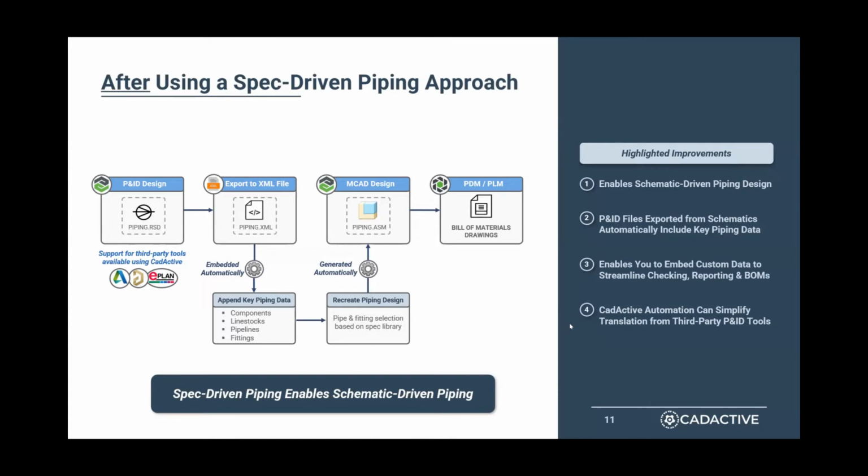Obviously processes at different companies are different. But a lot of folks that we run into build these P&ID process and instrumentation diagrams up front to determine what equipment and what components are going to need to be included in a model. What that doesn't include is routing information, bend radius information, additional information that you might need to gain from having this complete 3D representation of your model. So we want to make sure that that concept data makes its way into Creo regardless of what P&ID tool you might be using. Does that answer your question? Yes. Thank you very much.